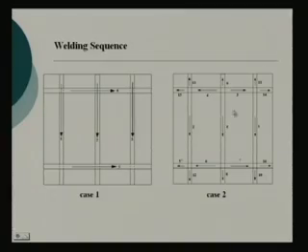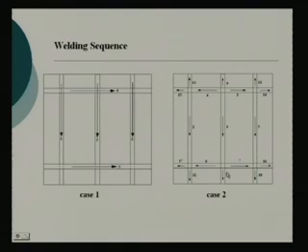Now, how do you balance? There are so many weldings. So based on that logic, one works out what should be the sequence. Like here you see I have done this 4, then I do the 5, I balance them. The vectors are just opposite, so each is cancelling the other, but when I do 1, there is nothing to balance this. So that is at the center I first do, right.